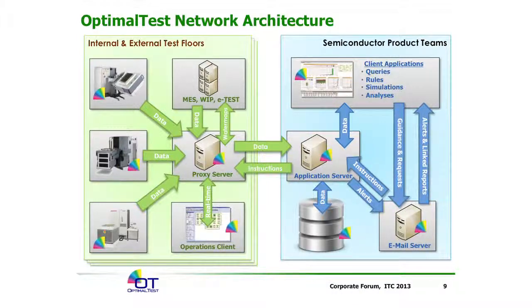So here on the test floors themselves, and again, in the internal or external supply chain, we install a software component called OT-Proxy. OT-Proxy is a very small software component. It has 2 primary tasks. Its first task is to monitor the tester and collect data log information. Its second task is to interact with the test program in adaptive test scenarios.